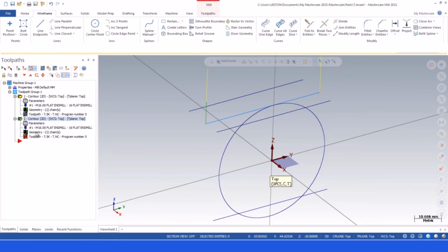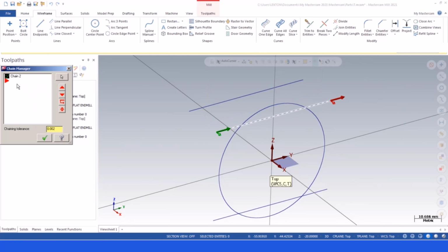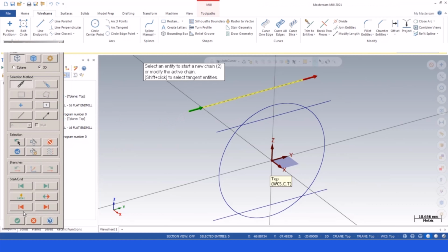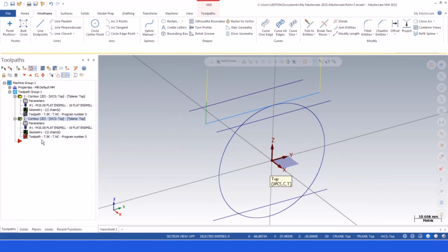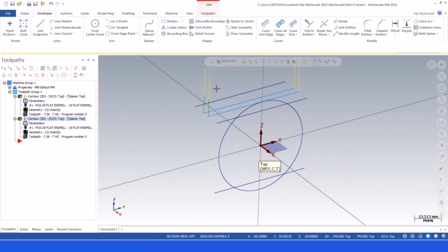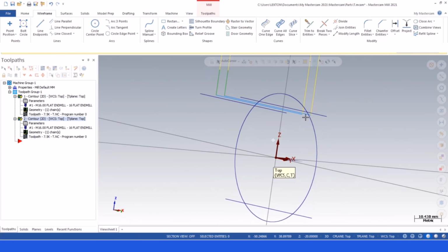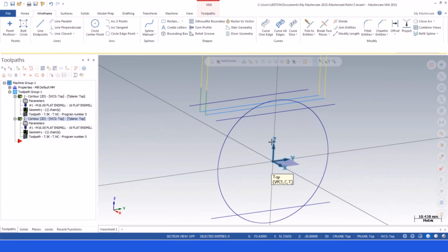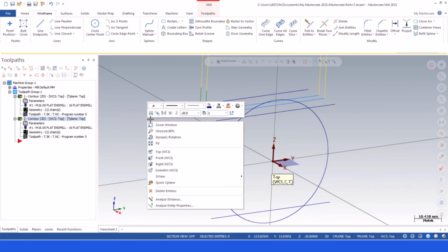So I'm going to click here to be able to change my geometry. Maybe you can also see that kind of options. You need to push the little plus button here, and then you can delete my chain and take a new one. So this is going to be my new chain here, and then we can recalculate. So at that point, we can easily get exactly minus 20 millimeter here. Okay, everything seems fine.